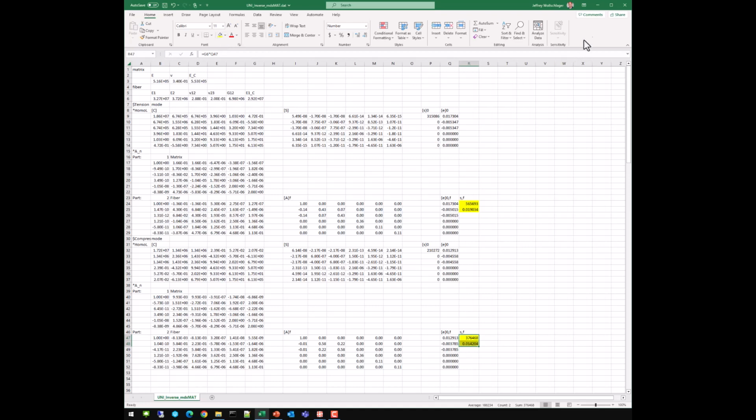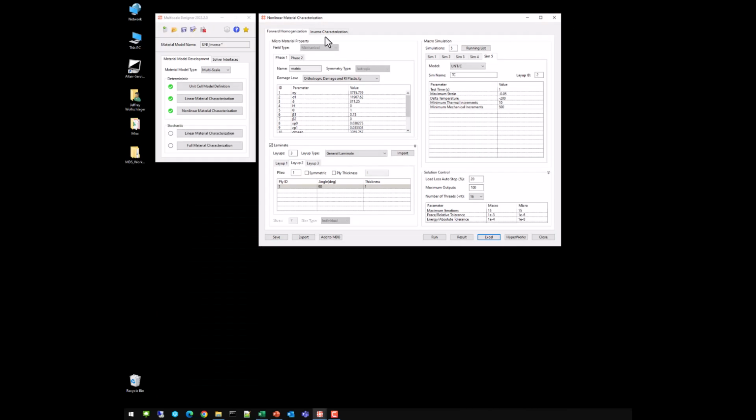So these numbers are the numbers that I want to enter into the damage law exactly. So let's go ahead and do that while we're on the fiber phase. So we can flip over to phase 2, which is our fiber phase, and we can enter in the tension and compression damage law properties exactly as calculated. I'm going to have 565 KSI at 0.17%.